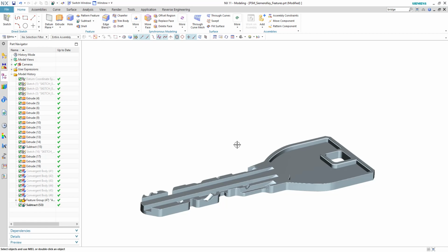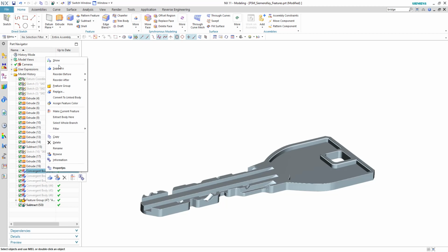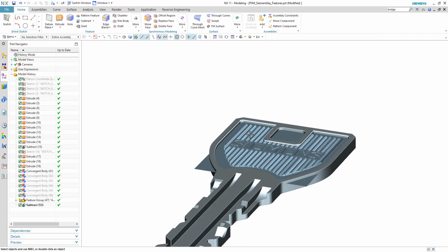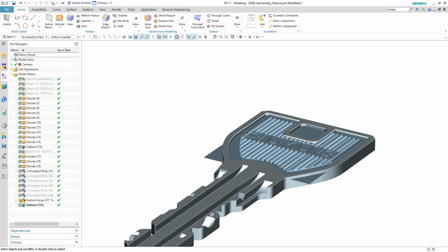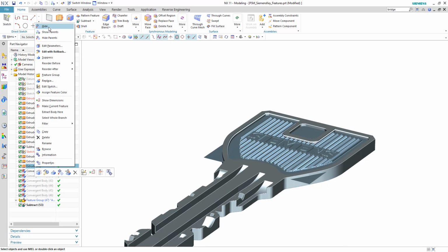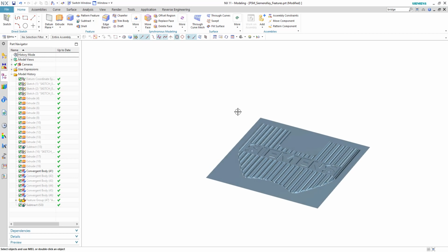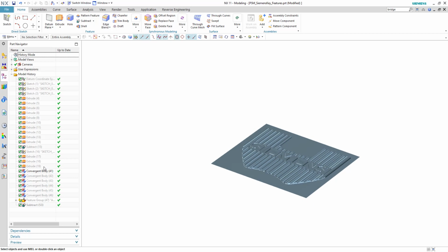So notice that it actually puts the key grip section in there, but there isn't any complex geometry from a bitmap file. So now we're going to look at the bitmap file before we actually trim our tool body and then do a subtract to implement it into our key. So the first thing we need to do is show our bitmap file that's been converted into a facet. So now I'll press show. So here you notice that it actually isn't on the key just yet, but this is the bitmap file that we're going to be using. Here I'll hide the key so we can see the bitmap file even better. So this is the complex geometry that we're going to be putting in that key grip section. So now I'll show back my key.